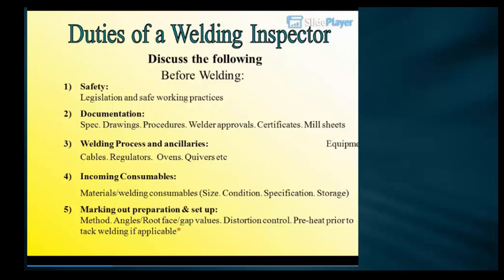Materials/welding consumables: size, condition, specification, storage. Marking out, preparation and setup: method, angles, root face/gap values. Distortion control. Preheat prior to tack welding if applicable.